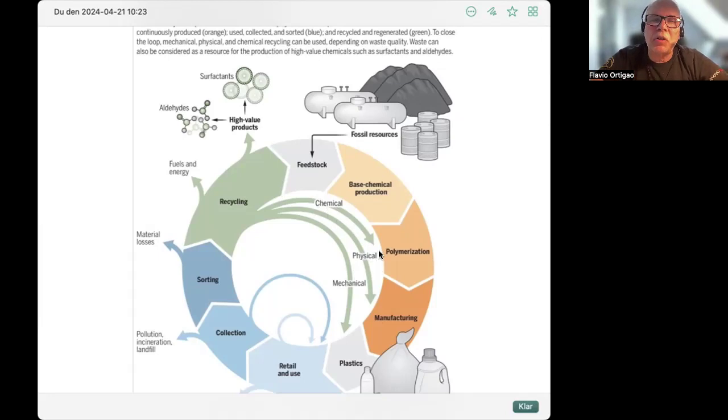Well, in pyrolysis, you produce three phases: a gas, a solid phase, and an oil, the pyrolysis oil. And if you can use this pyrolysis oil to fish out the monomers and repolymerize, that's a very good option. But be aware, pyrolysis is by no means a simple thing. The pyrolysis oil contains all the homologous series of plastics. And this goes from C1, the carbon, to C32, the wax, and every same mixture.